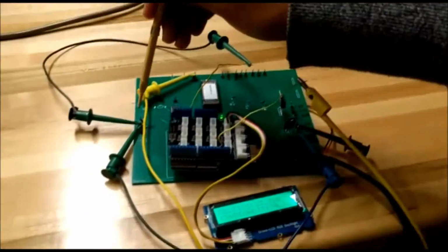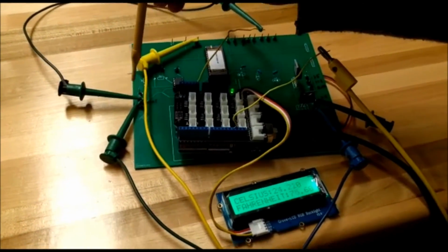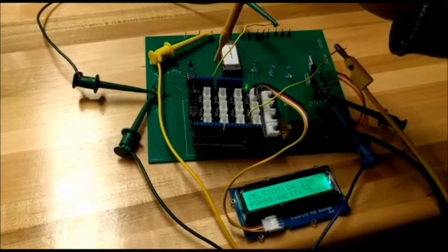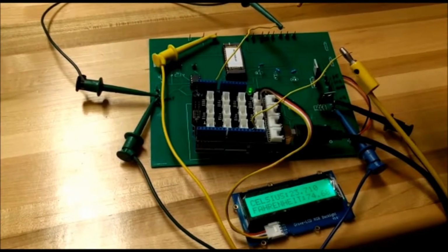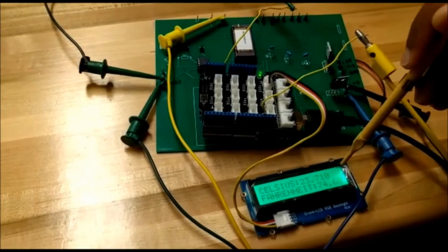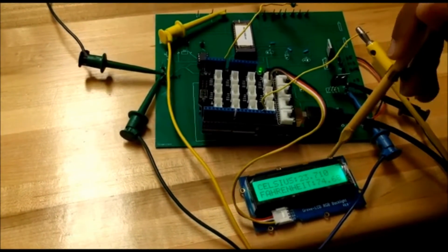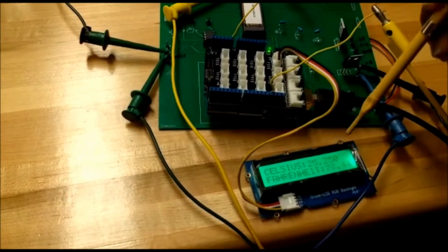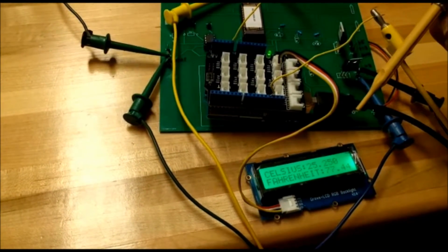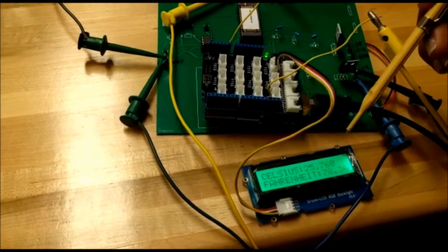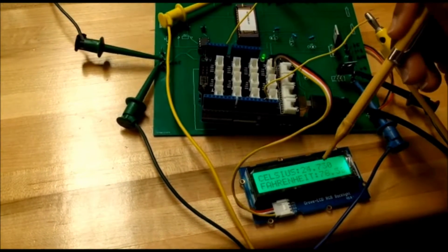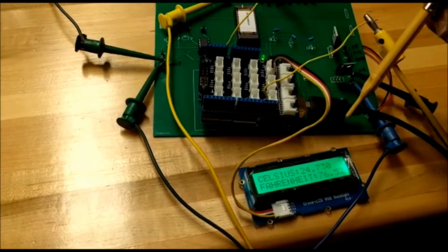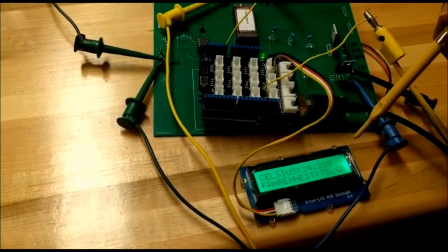We are then feeding the PTAT output voltage from this pin into an Arduino, and we are calculating the output temperature based on the curve that we obtained. As you can see, the Arduino gives a temperature between 23, 24 and 25. This is a fluctuation that is expected, and we are predicting a temperature accuracy of 2 degrees Celsius.